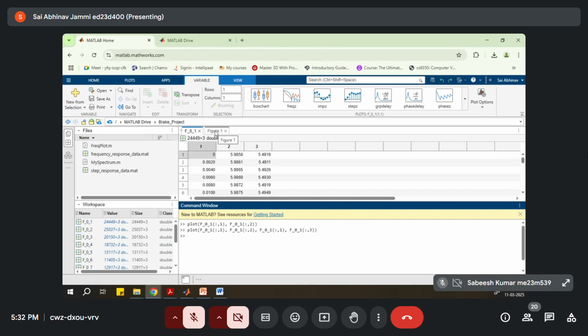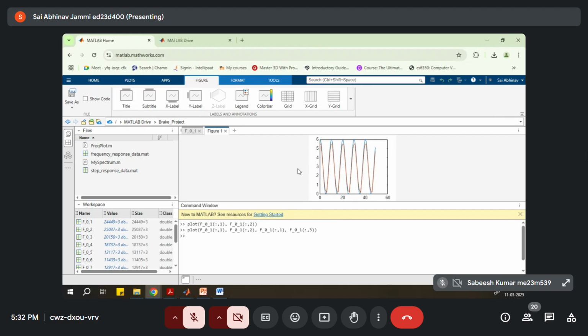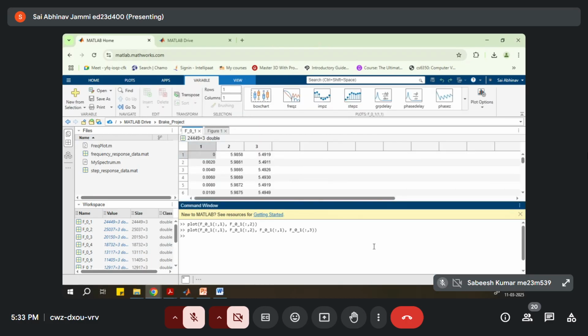So here we have plotted the time varying plots of the input and output. Right now, see what is our aim. We want to see what is the one condition for a linear system. When we give an input at a given frequency, you must have learned in the introduction to Bode plot lecture, that the output will also be at the same frequency, for a linear first order system, right?